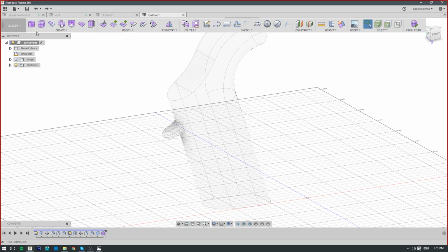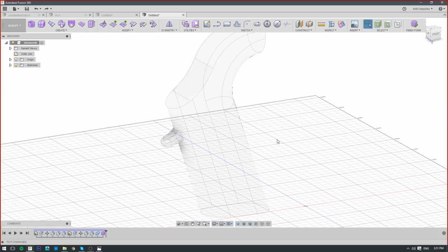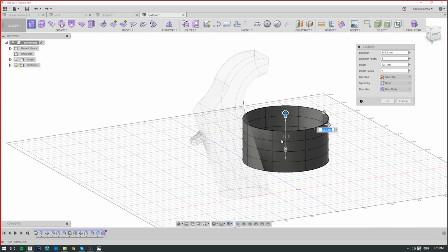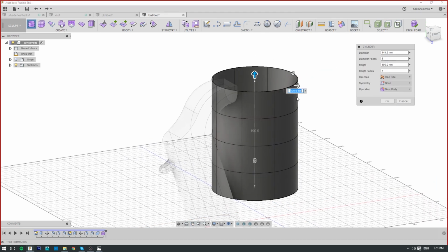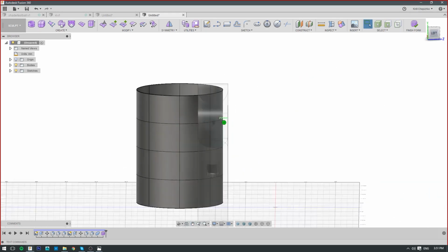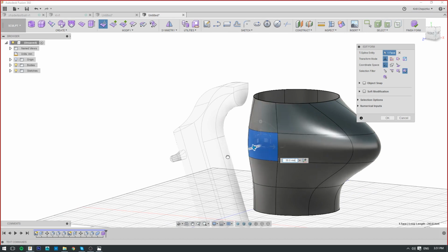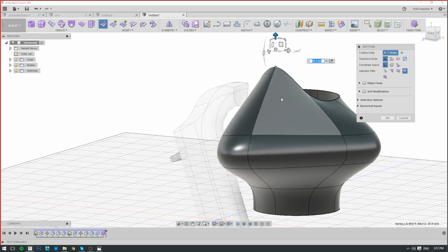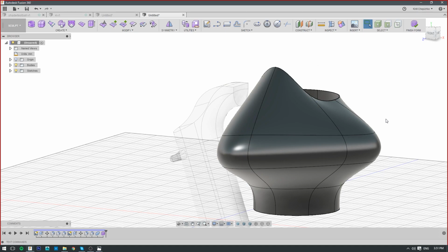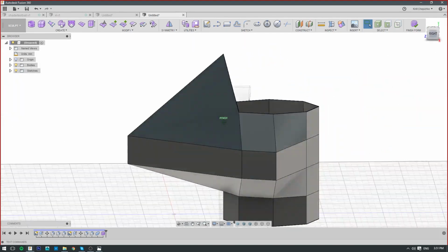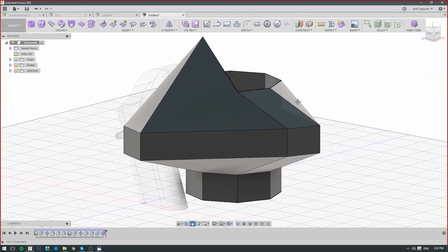Because the sculpt environment that we just went into, which we will talk about in the third lesson, imitates sub-D because you're counting your edges. In case somebody didn't understand what's happening here, when we look at the sculpt environment, yes, you can pull them out, it looks soft and gooey, and you pull on vertices and faces and edges. But what's happening in reality, if you press Alt-1, is the unsubdivided version of that. It's a box mode, right? So it's exactly how it would look in sub-D.